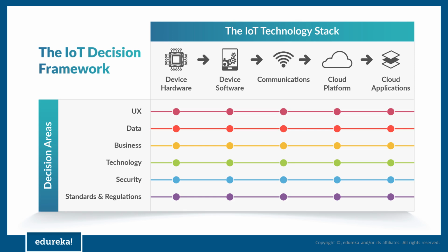This is how you see the difference between the architecture of regular software and IoT software. Huge difference, correct? Here you're talking of device hardware, device software, communication channels. So there are multiple ways of communicating. Your sensor connects to your gateway maybe through hardwire, like our Sense HAT is going to connect to our Raspberry Pi using simply GPIO pins, which is hardwired. Somewhere you'll see it is using Bluetooth. Somewhere within a factory area, it could be across an acre, so you'll use some technologies like LoRa. You would have heard of LoRa or LPWAN. They are long and short range transmission communication protocols.